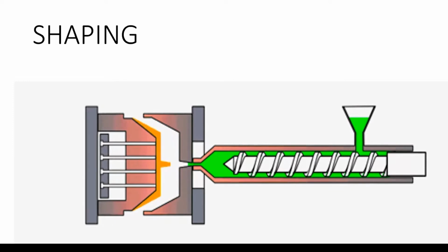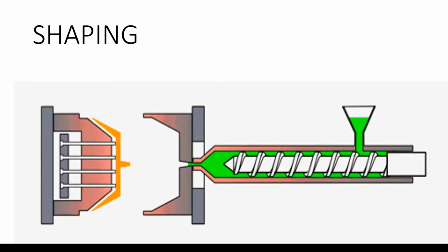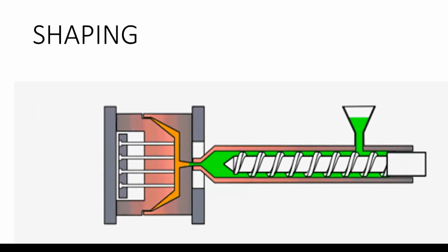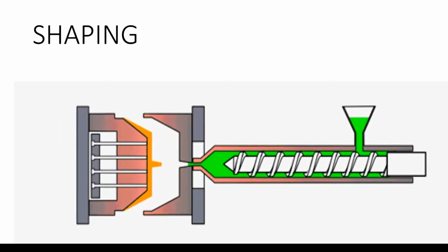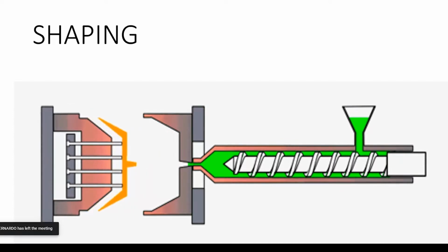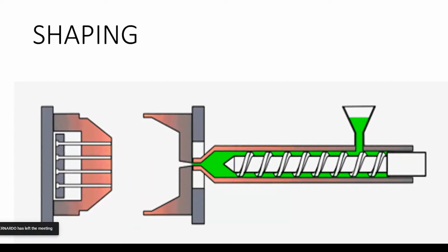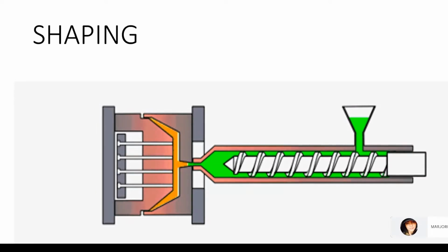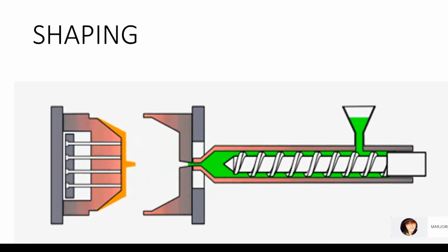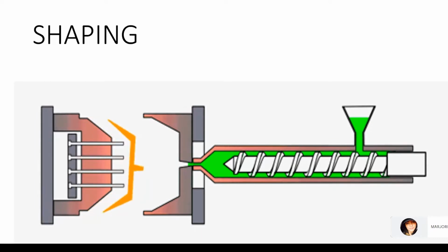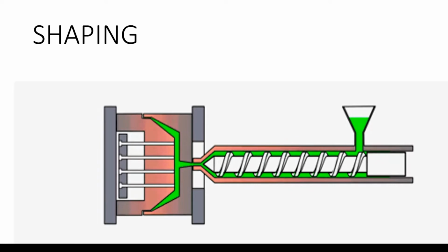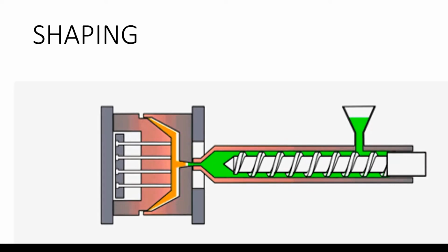Extrusion consists of forcing highly plastic rubber through a series of screw extruders. Calendering passes the rubber through a series of increasingly smaller gaps between rollers. The roller die process combines extrusion and calendering and produces a better product than either individual process. Coating uses a calendering process to apply a coat of rubber or to force rubber into fabric or other material.